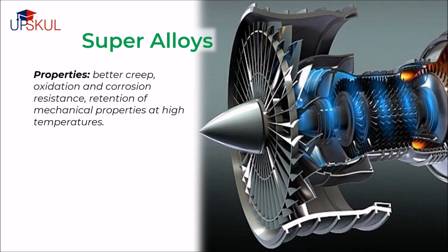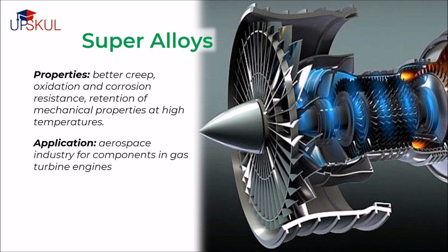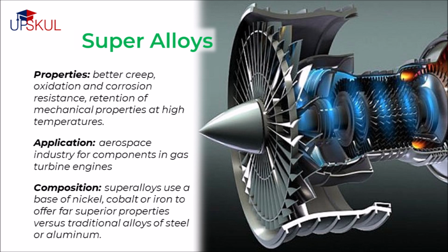Superalloys are a group of metals that offer better creep, oxidation, and corrosion resistance than traditional alloys, while retaining excellent mechanical properties even at high temperatures. In a sense, they act as high-performance alloys. Commonly used in the aerospace industry for components in gas turbine engines, superalloys use a base of nickel, cobalt, or iron to offer far superior properties versus traditional alloys of steel or aluminum.